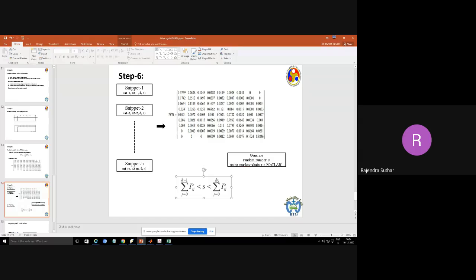That value will be the k value, so the snippet belonging to this k value will be the next snippet. We continue this iteration till we reach the complete length of the drive cycle. So this is how this drive cycle is made.